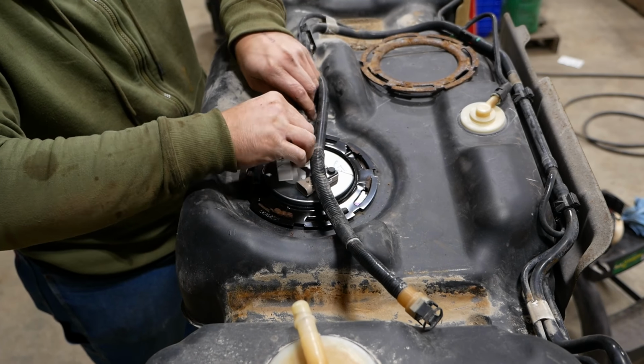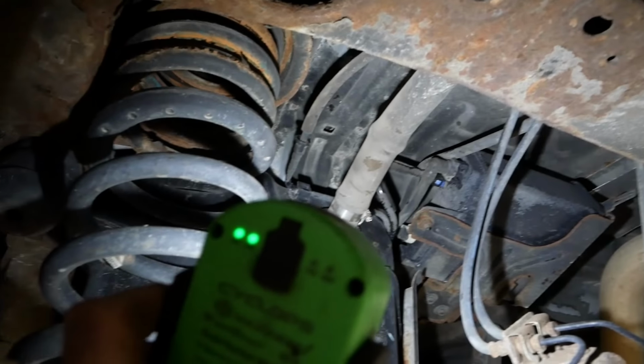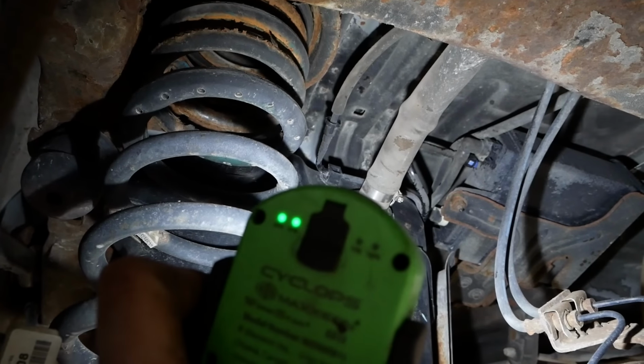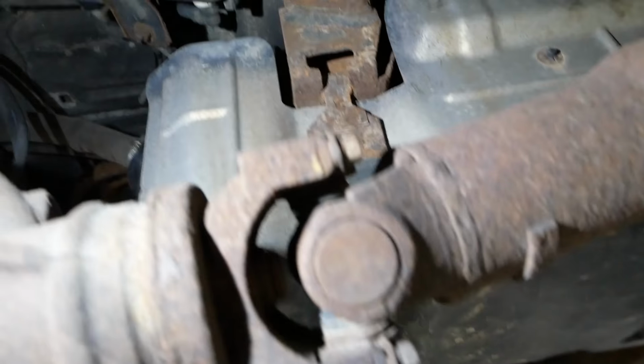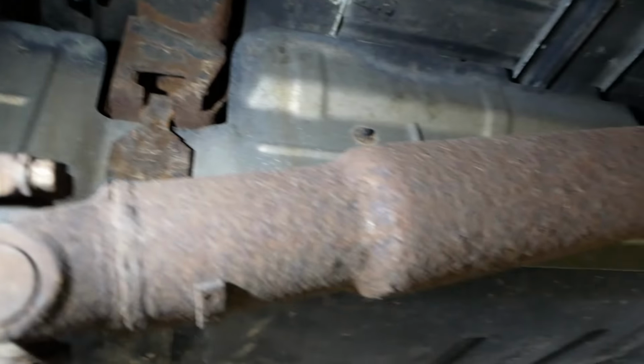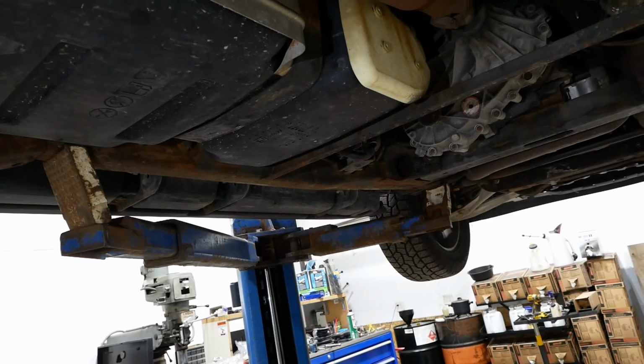All right, folks, got her installed. This job should be done. Got one connection there at the front, and then everything else is at the back. So we got two for the filler neck and two up there on the charcoal canister. There's one supply line on the fuel pump and a couple of wiring connectors. Yeah, it's a pain in the ass to get this thing out, but putting it back in is a breeze. Of course, it's designed to go in. It's not really designed to come out. Everything just clips together. Yeah, let's set her down, see if we still have a leak.